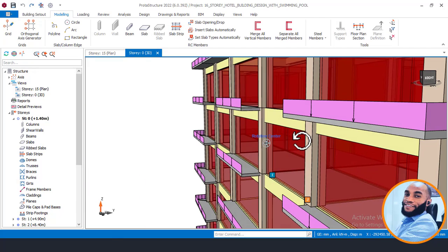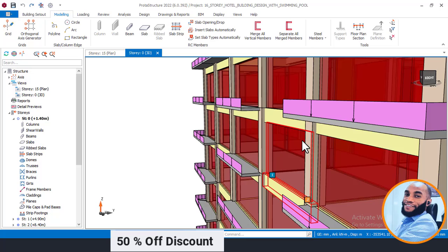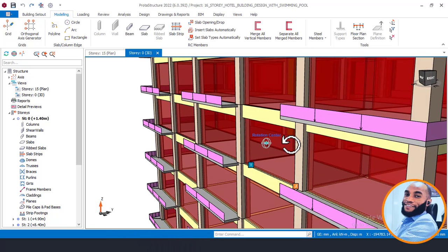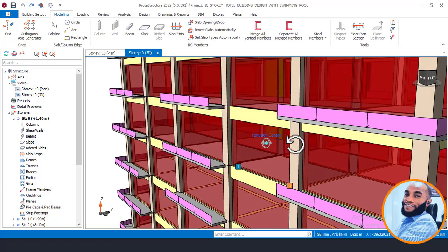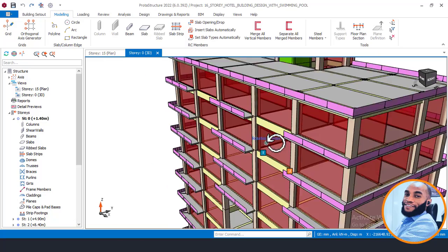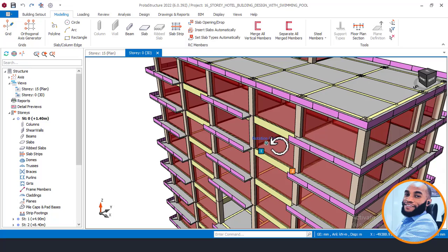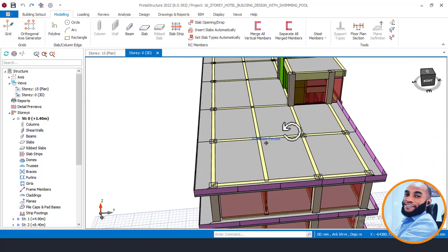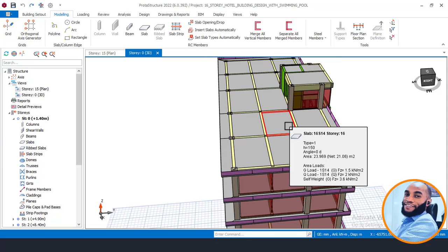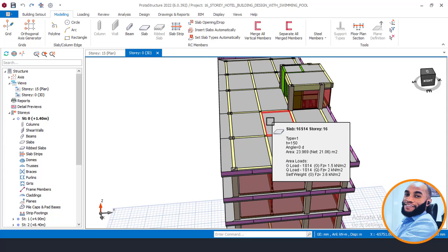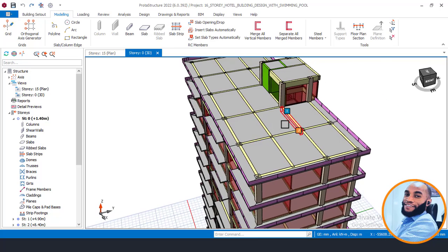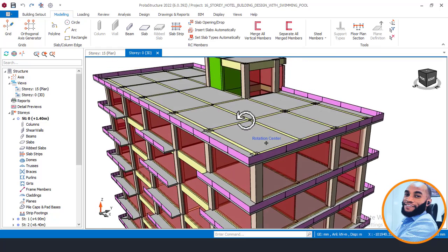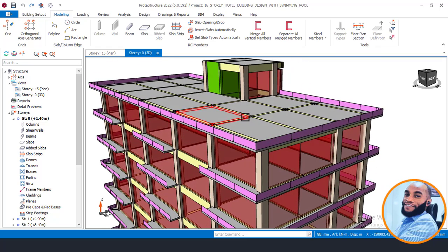Okay. Now, knowing that the block work method used to reduce load is not going to work on this hotel building, the next thing you have to consider is to change the type of slabs. Knowing that we have different types of slabs when it comes to reinforced concrete design, we have what they call solid slab, which we have used here, and then we also have rib slab, waffle slab, and flat slab and all that.